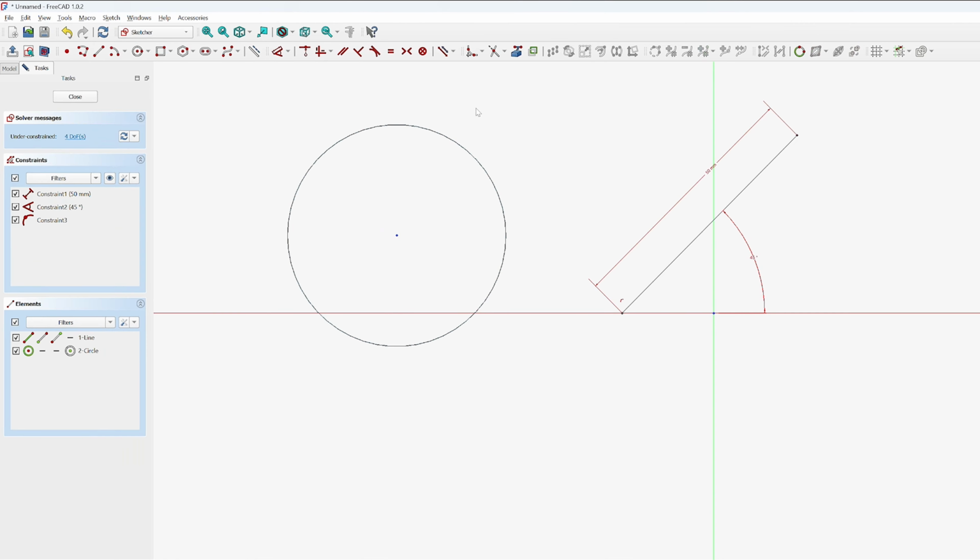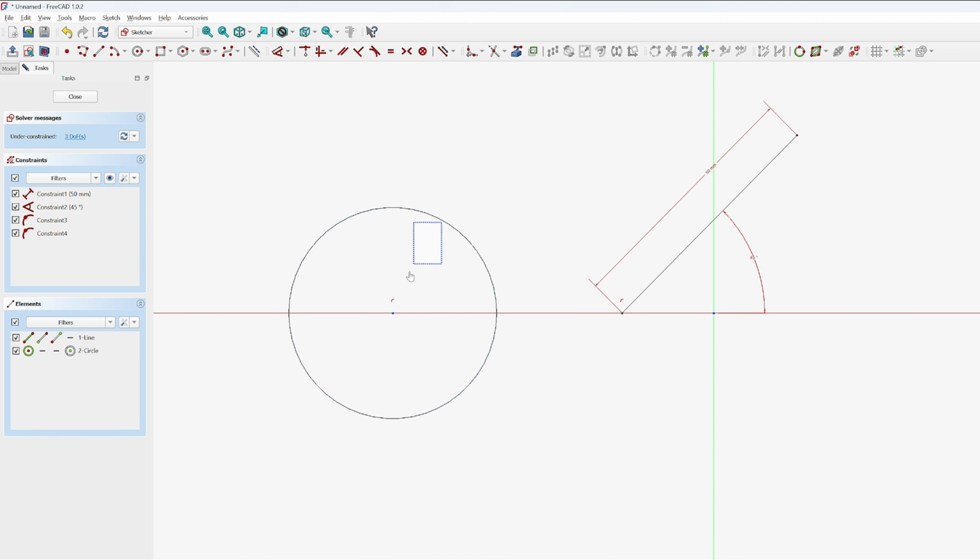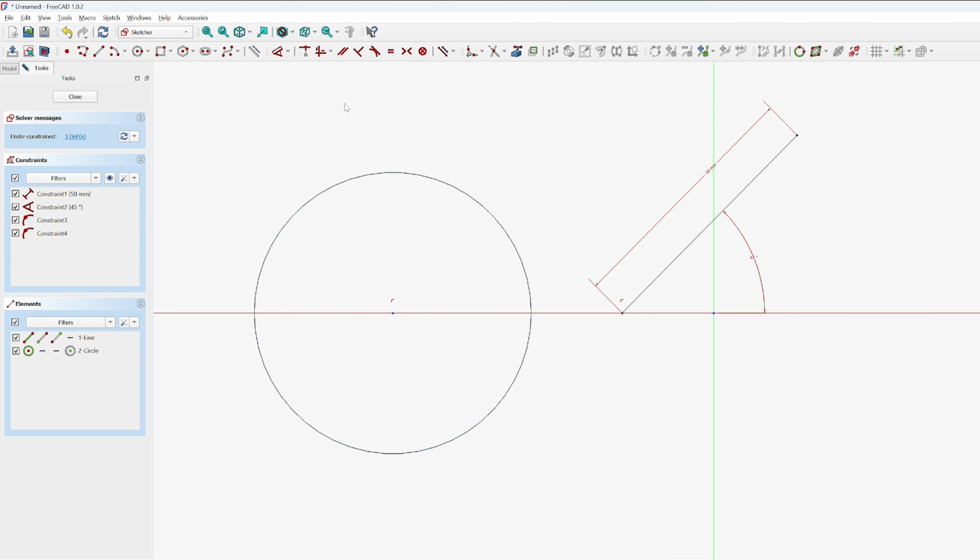So here you can see this is a circle, and again maybe I can use some geometric constraint. For example, here I'm thinking of using coincident, which will make this circle lie on the x-axis. Now of course I can move it along the x-axis, but it won't go in any other direction. But there is one more thing which is still variable, which is the diameter of the circle. So let's also try to control the diameter,